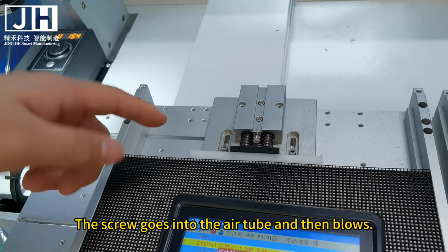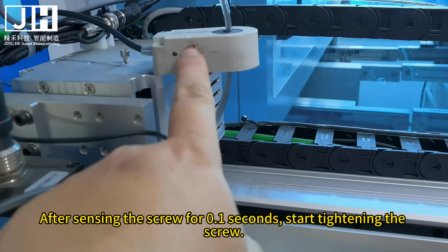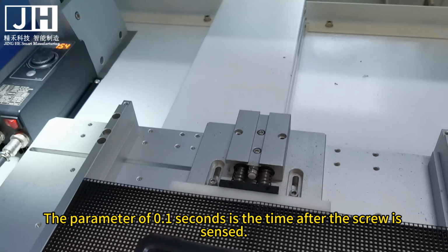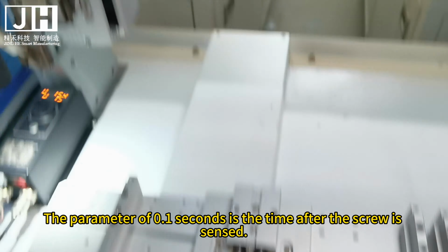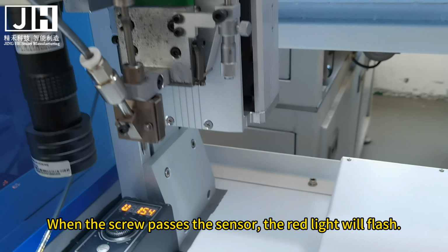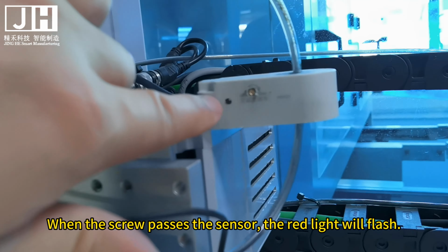The sensor detects the screw and starts counting time. After sensing the screw for 0.1 seconds, start tightening the screw. The parameter of 0.1 seconds is the time after the screw is sensed. When the screw passes the sensor, the red light will flash.